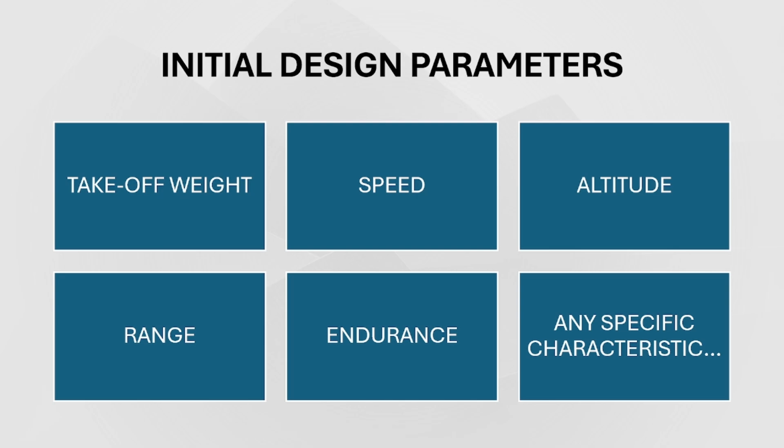You can actually calculate that takeoff weight from payload, and by using some engineering books and manuals you will be able to define, for example, maximum takeoff weight and all the other weight parameters, which is actually another interesting stage of aircraft design. But for simplicity, for the beginning, let's think of some kind of weight and not touch the weight calculations.